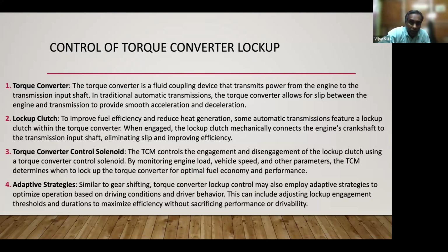And torque control solenoid switches are available. That is, we call it as the lockup clutch for engagement and disengagement of lockup clutch. These control solenoid valves are used. So they will just keep track of the engine load, vehicle speed, and other parameters, and it will determine whether you have to engage the lockup clutch or disengage the lockup clutch, so that you will receive an optimal fuel efficiency and very good performance.